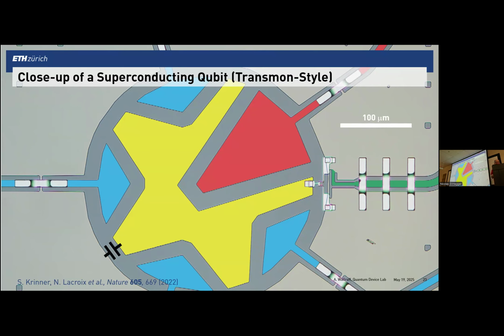What is the width of the oxide in that? Okay. So the tunnel junction oxide thickness is very small, or it's even hard to measure how large it is. Nominally, you can try to estimate it from the junction area and the critical current density that you get. I'll probably say something that is wrong. It's kind of on the angstrom or tens of angstrom level, and the